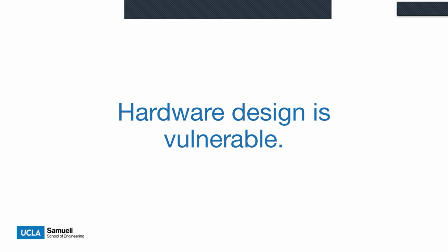And the prominent method of designing digital circuits utilizes RTL as the hardware description language, which is the register transfer level code. For this reason, designers are required to specify the microarchitectural elements completely, cycle by cycle.